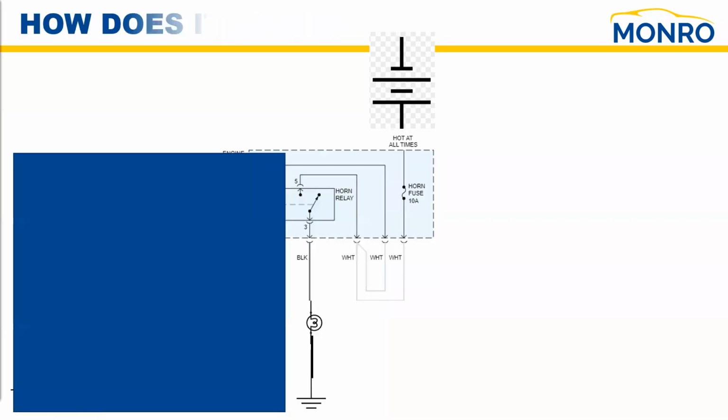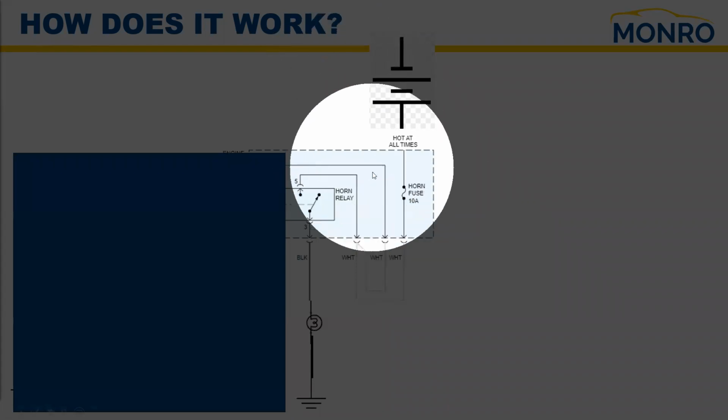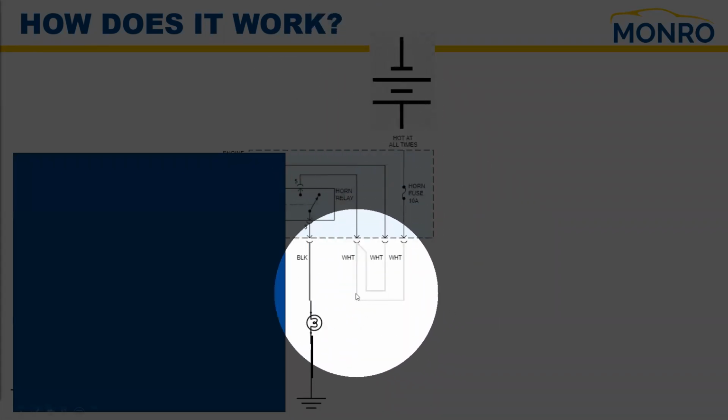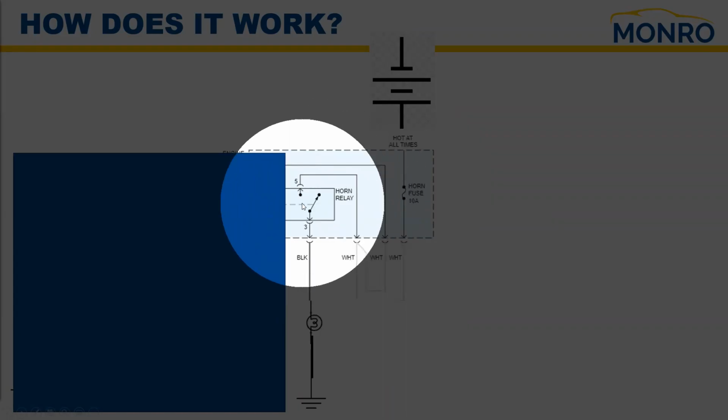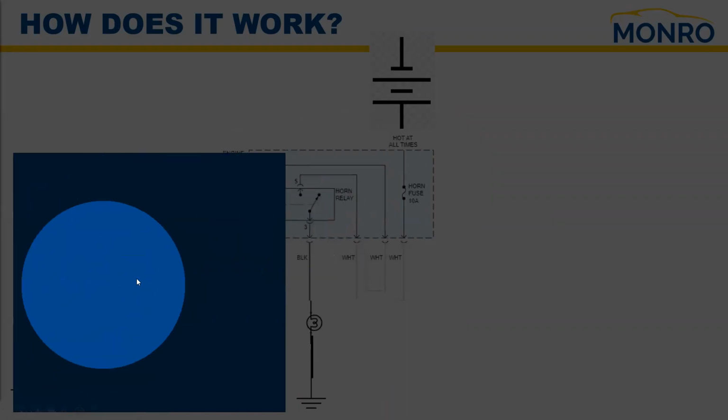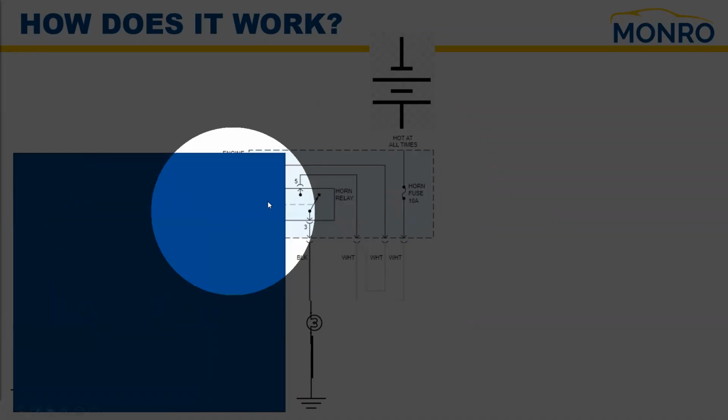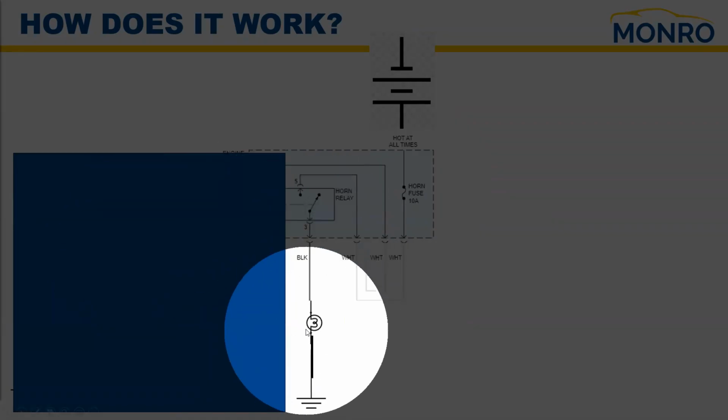On the other side of the circuit, what were we looking at? That was the controlled side. We had battery positive power coming into this horn relay. We ran battery positive power up over to the switch. As soon as we energized that low current coil that we hid for now, we closed the switch, we honked the horn, we turned on the light, we powered up the fuel pump.